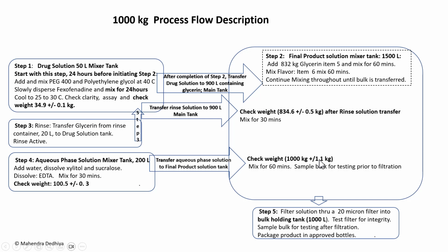Filtration is done to remove particulate matter, not undissolved solutes. Filter the solution through a 20 micron filter into the bulk holding tank. Test the filter integrity. Sample the bulk after filtration for testing according to the QC procedure and package the product in approved bottles.